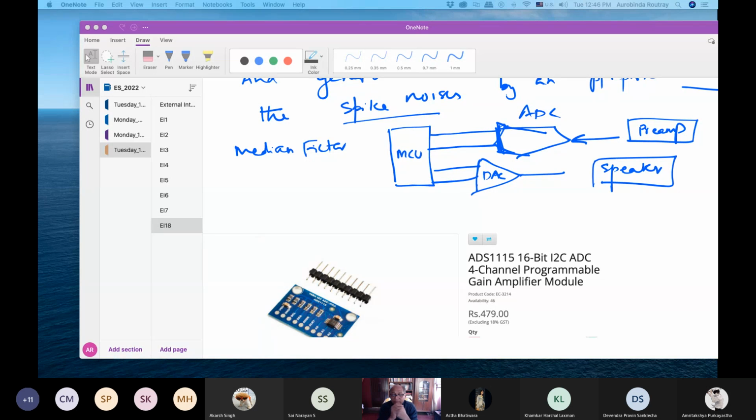It's very easy. Making input, output ports. So two ports, port B, port C, 8 bits. So both you will connect. Then when the AD conversion is complete, you have to use an interrupt, one of the external interrupts. Whenever the AD conversion is complete, you read the 16-bit number, right?